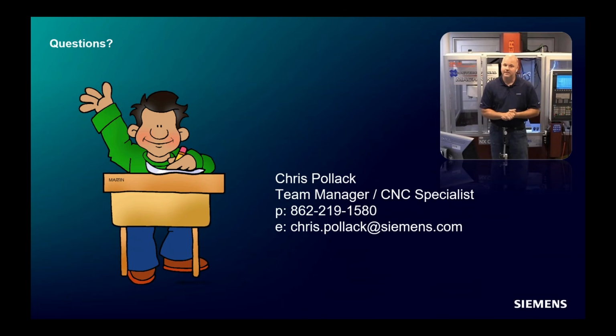And then programming from the control. We had a question here: is it programming from the control? I think you touched base on this in the webinar. You can do it from the control, and you also can do it through CAM, so you have a couple choices there. From your CAM system, Cycle800 is posting out the same mask that you would see on the control, as you would see in a posted program. Yeah, good point.